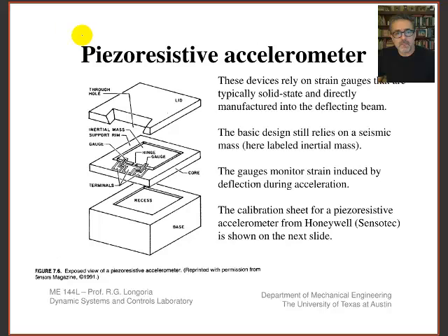We have studied strain gauges, which are piezoresistive. A lot of the accelerometers you can buy out there are piezoresistive, kind of like strain gauge type, and these are made using microelectromechanical structures. The pressure transducer we used was piezoresistive, with a strain gauge embedded in a diaphragm. Here you have the equivalent of a small little beam with little hinges, and little strain gauges on it, and this is your vibrating mass.